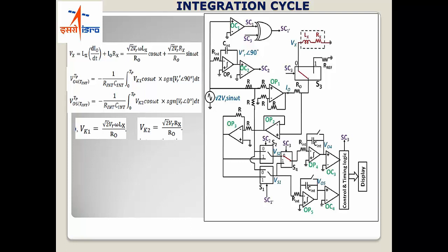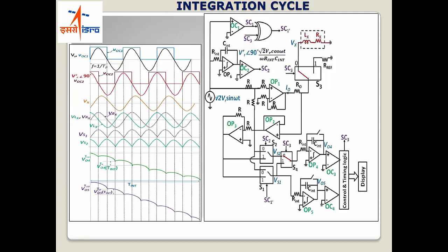So you get a function of cos as well as a function of sine over here. The cos component contains the terminology of the unknown inductance. The sine component contains the term of the unknown resistance of the element. So going back, this is how the waveform would look, and it consists of two portions, one proportional to the sine component and one proportional to the cos component.